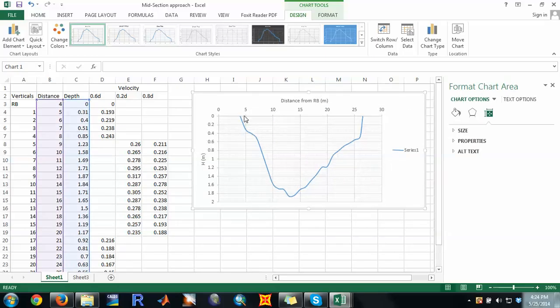So we can divide this river valley into several cross sections. Then for a single cross section we can take a velocity measurement, and velocity measurements can be taken at 0.6 d or 0.2 d or 0.8 d. So usually at the banks of the rivers, this place and this one, we measure the flow velocities at 0.6 d, and for the central sections where you have larger depths, you measure the velocities at 0.2 d from the surface and at 0.6 d from the surface. d represents the depth of your river at this particular point.